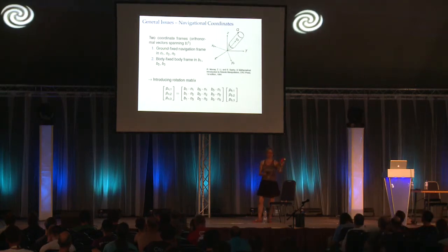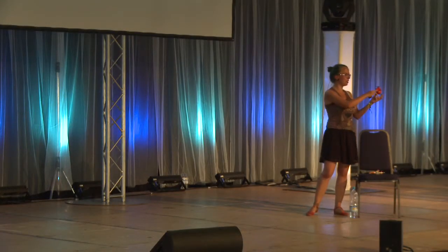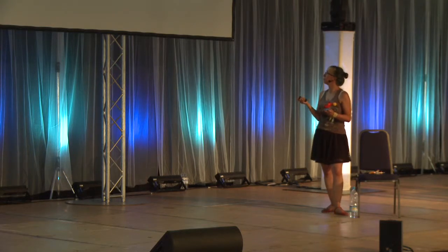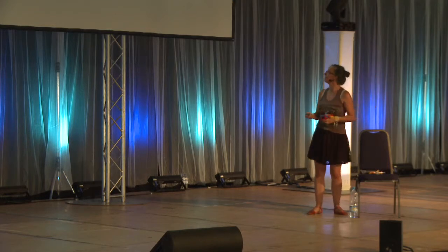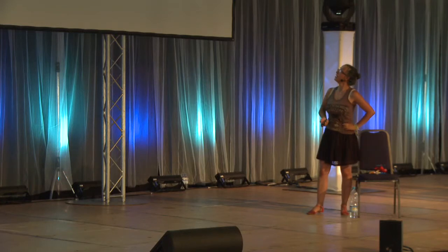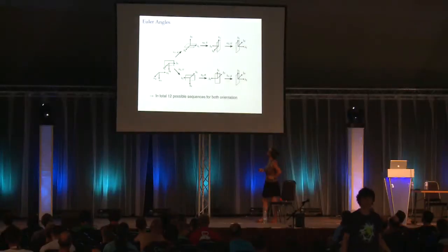Sorry. And you have to rotate your ground fixed frame, which is inertial, to your body fixed frame, which isn't inertial. You usually do that by a rotational matrix, where you project, indicated by the dot product, your ground fixed frame, all your GPS coordinates and everything, to the helicopter so that it knows its orientation. And the standard approach would be just to use Euler angles for that.